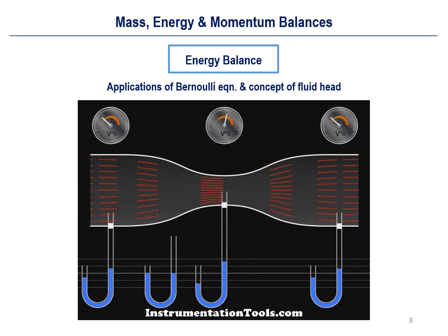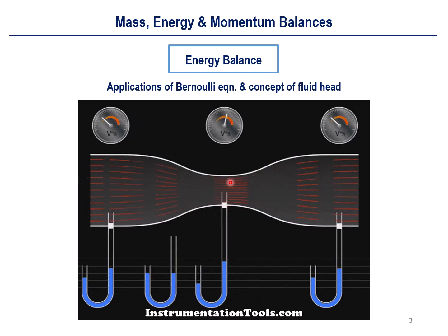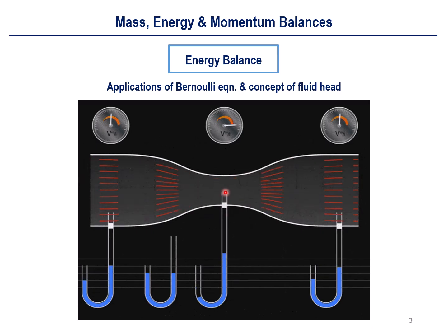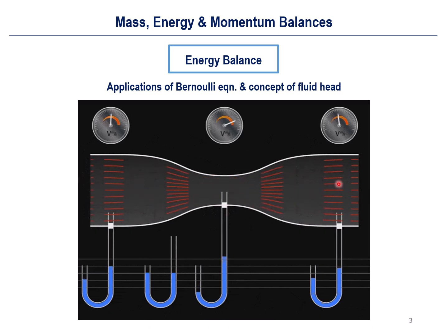At the inset, you can see that there is a relatively larger cross-sectional area here. But in the vicinity of the orifice hole, we have a contracted cross-sectional area. Due to this contraction and mass conservation, the flow velocity is much greater than the initial fluid velocity.